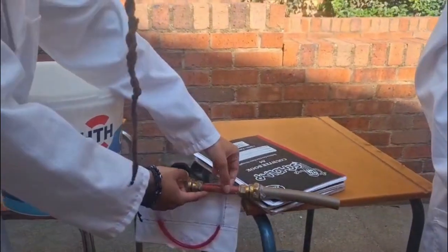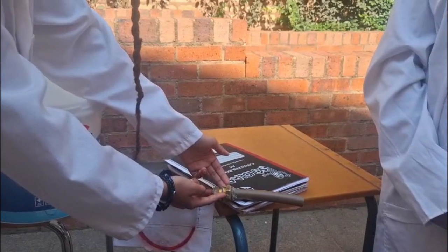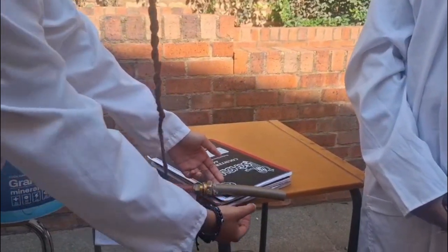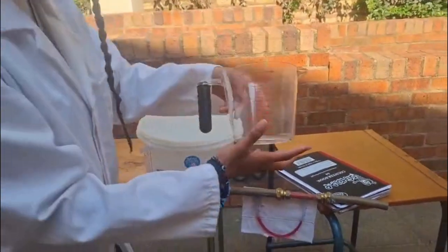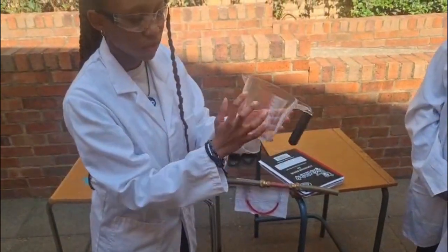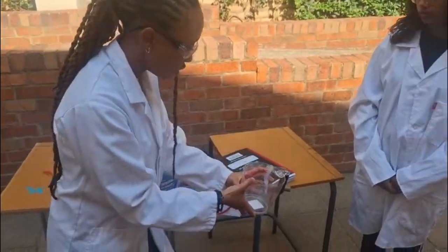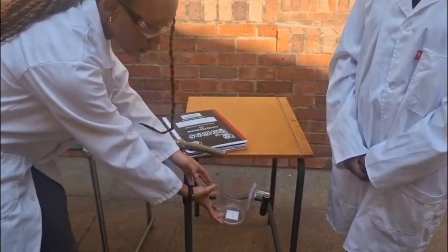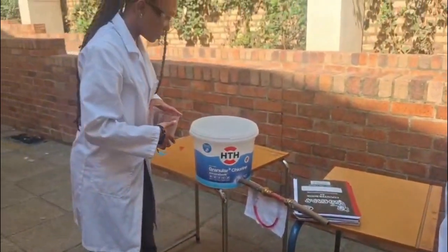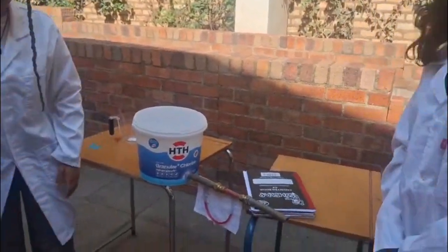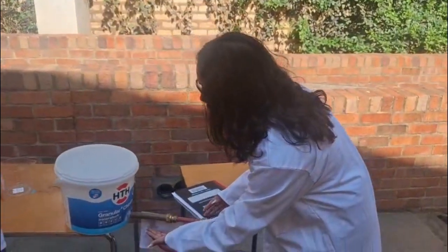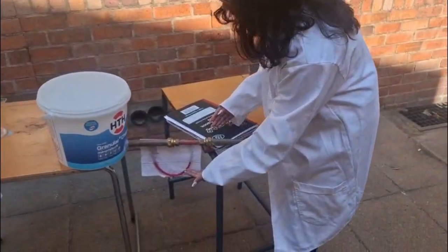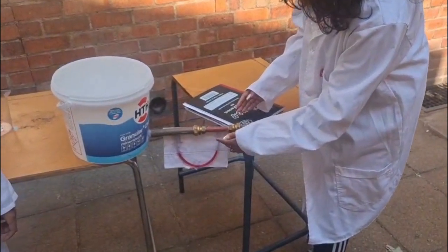Downstream of the contraction, the pipe returns to its original 22mm diameter, creating an expansion region where flow deceleration occurs. Finally, the discharged water is collected in a 1-liter measuring jug placed at the outlet. This enables us to verify the volumetric flow rate by timing how long it takes to fill the jug. A U-tube manometer was constructed using glycerine as the working fluid. The glycerine was dyed red for visibility reasons.